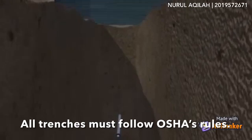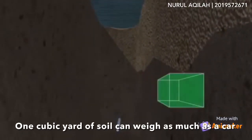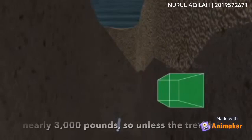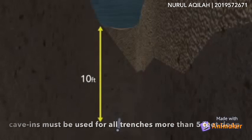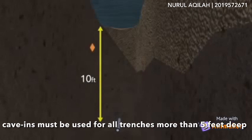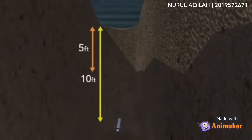All trenches must follow OSHA's rules. 1 cubic yard of soil can weigh as much as a car, nearly 3,000 pounds. So, unless the trench is in stable rock, a protective system must be used for all trenches more than 5 feet deep, or for any trench that shows signs of caving.